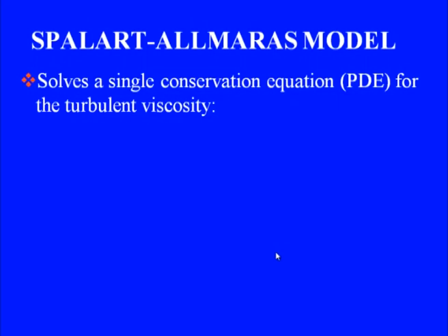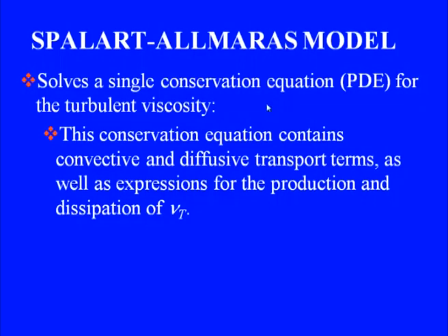Okay, next category, the Spalart-Allmaras model. We will not have a look at the algebraic details because it is a very specialized model for aerodynamic calculations, and it is a one equation model because it solves a single conservation equation, or one PDE, for the turbulent viscosity. This conservation equation, which has been derived for aerodynamic flows, contains a convective and diffusive transport term as well as expressions for production and dissipation of the turbulent kinematic viscosity.